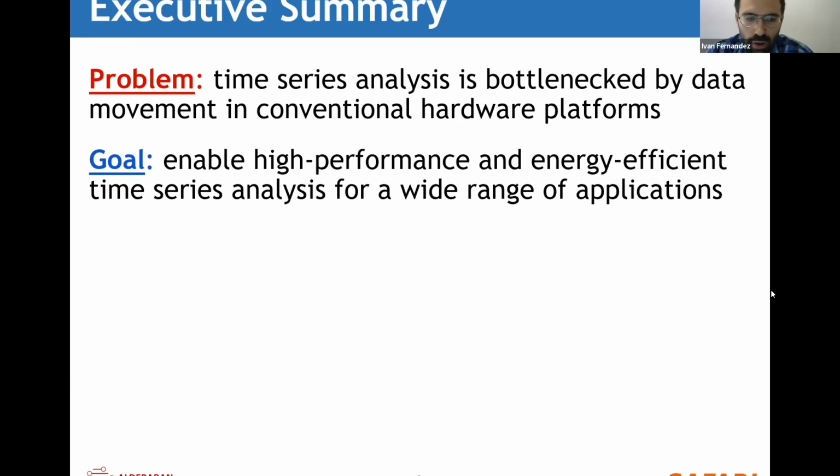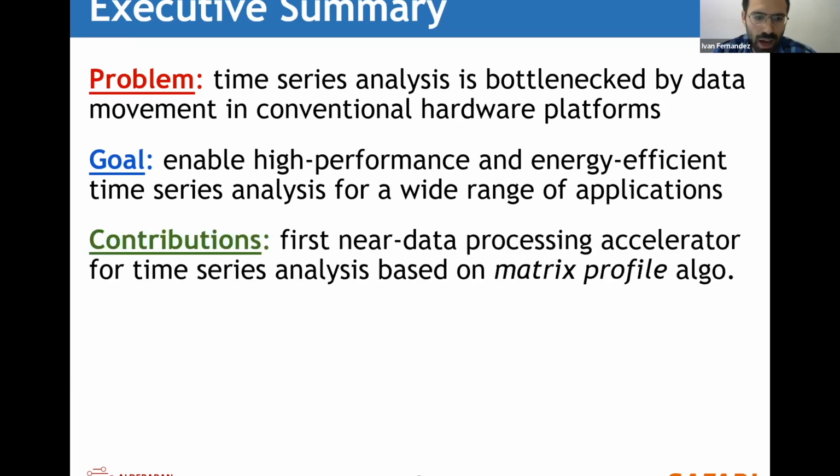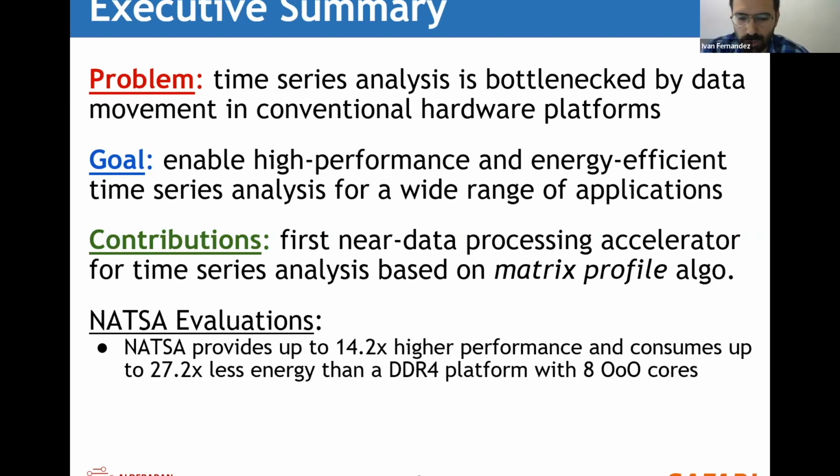And the goal of this work is to enable high performance and energy efficient time series analysis for a wide range of applications. As contributions, we propose the first near data processing accelerator for time series analysis, which is based on the matrix profile algorithm. NATSA evaluations show that it provides up to 14.2 times higher performance and consumes up to 27.2 times less energy than a DDR4 platform with 8 out-of-order cores.